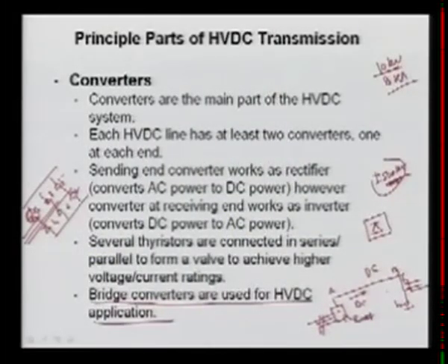This is a bridge converter using thyristor valves, and it is your rectifier, and at the inverter end we also use the bridge converter. Again, whether it is 6 pulse or 12 pulse depends upon your power rating, your harmonic filter, etc. So it is decided based on that.